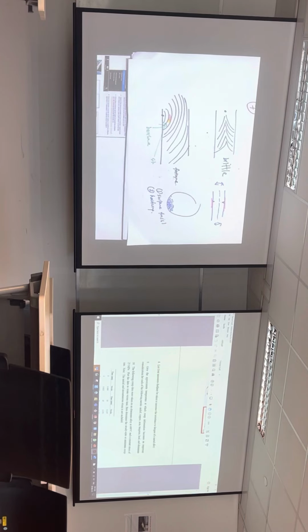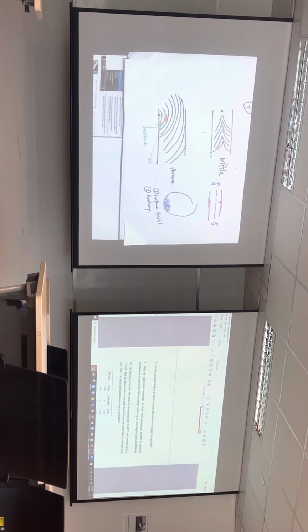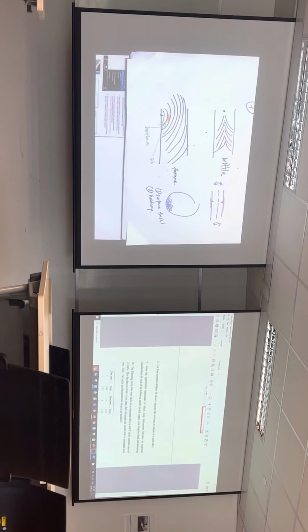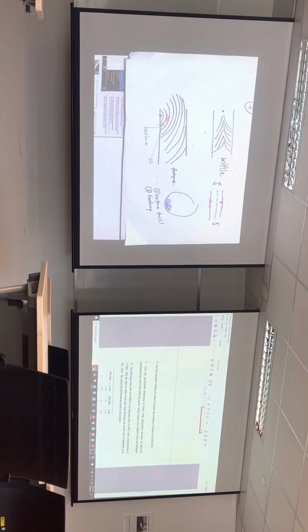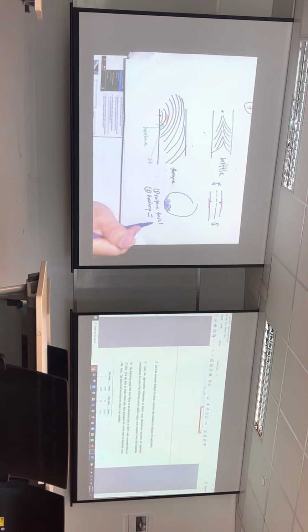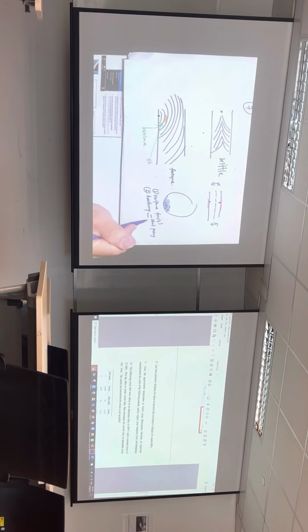When people do shot peening, it is to protect. For example, I think I showed you a video about the landing gear. Landing gears are subject to fatigue every time, up and down, so it is to protect the surface from accidental scratches. The other one can be carburizing.